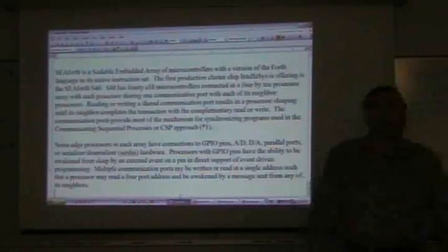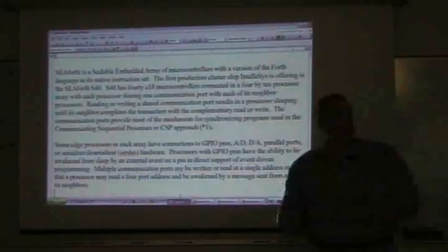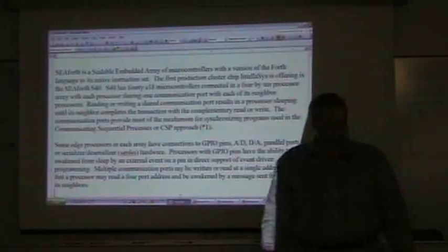And normally you have to implement this as a software layer, unless you're dealing with something like the Transputer, which was a hardware implementation of the Occam language and the CSP, and it had hardware communication ports that, like ours, let one processor go to sleep until the other processor that it's talking to responds.